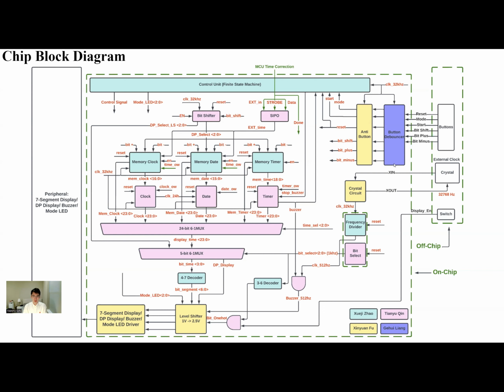The overall process includes, but is not limited to, RTL simulation, then logic synthesis, and also post synthesis, using Cadence Innovus to do automatic place and route: import, floor plan, place, clock tree synthesis, automated optimizations, route, and export.